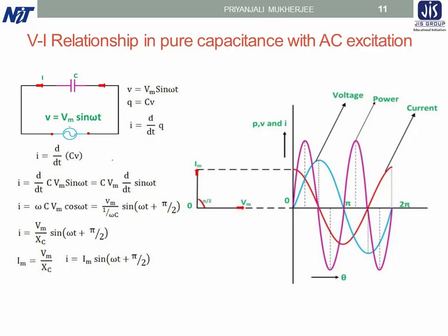The energy taken from the supply is stored in the capacitor during the first quarter cycle and returned during the next. So the energy stored by the capacitor at maximum voltage across its plates is obtained as half of C V square. And this can be realized when it is recalled that no heat is produced and no work is done while current is flowing through a capacitor. As a matter of fact, in commercial capacitors, there is a slight energy loss in the dielectric in addition to an I square R loss due to the flow of current over the plates having definite ohmic resistance.